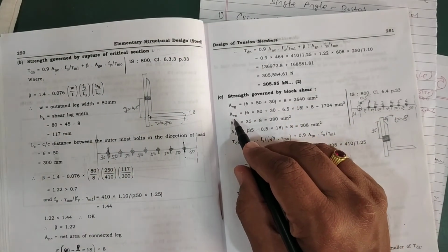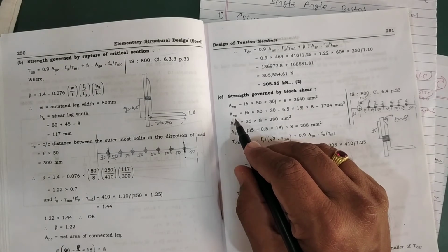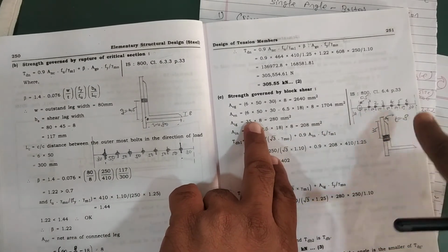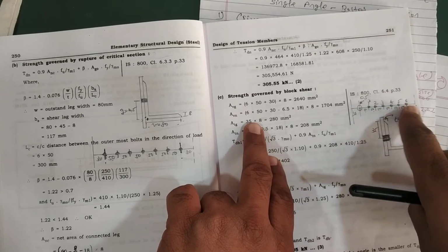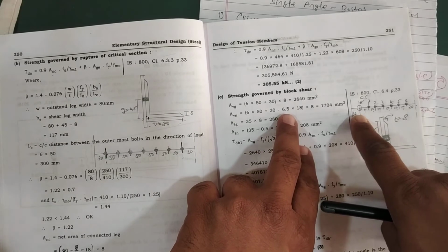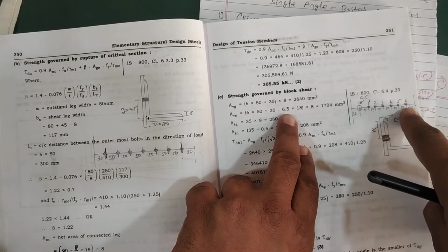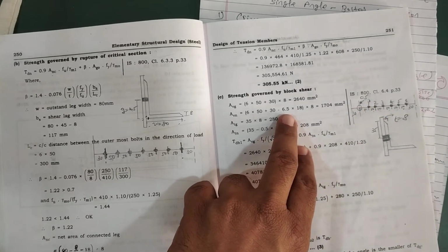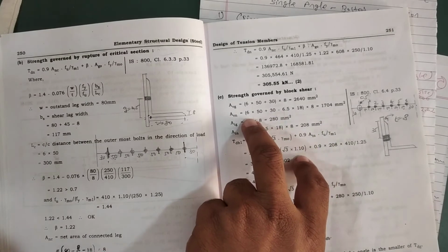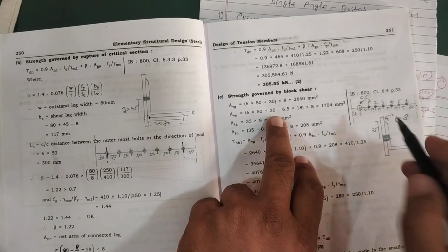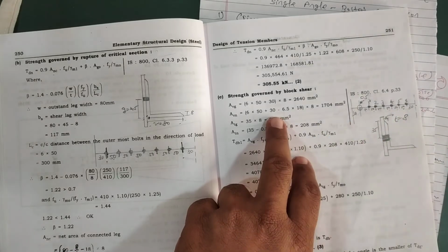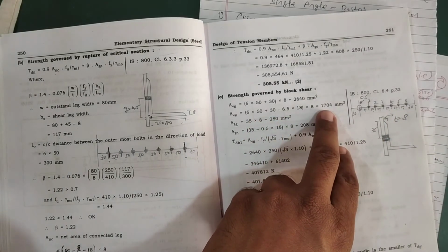Okay, fine. What is AVN? That is the net area in shear. So how is the net area calculated? You must deduct the area of the holes. Six are complete holes and half is another hole, so the total number of bolt holes is 6.5: 6 complete, 1, 2, 3, 4, 5 and 6, plus 0.5, so 6.5. What is the dia of a hole? 18. This must be deducted from the total length. What is the total length? 6 into 50 plus 30. So from here to here, minus this hole, 6.5 holes. Okay, fine. So this is the way you can calculate AVN.